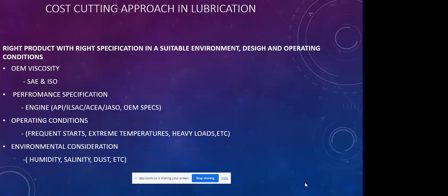You get the viscosity right and you get the specification wrong, then you are not doing proper lubrication. And these are areas where maintenance and reliability practitioners must focus, to save the company some money. Equipment that is supposed to run on an SP specification, using engines as an example in this instance, would do longer drain intervals than going in for an SF or an SD specification. So it makes the specification conversation very, very crucial in reliability and asset management.